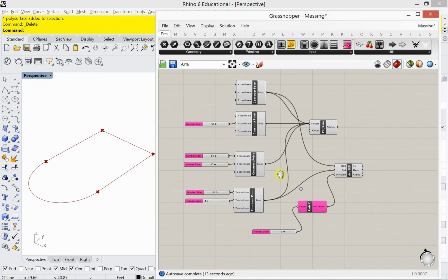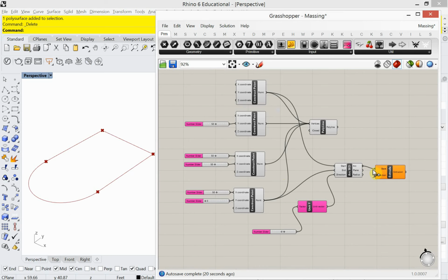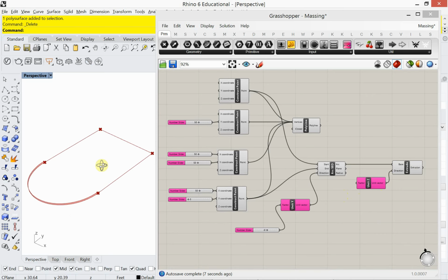Okay, and then you can do things like extrude. And just remember that extrusions are not going to cap automatically, so I'm double clicking and I'm putting in a z height for this. Alright, I'm glad I went to extrude this because you see it's only extruding the arc. The arc and the polyline are not joined together. So the first thing I need to do is join the curves.